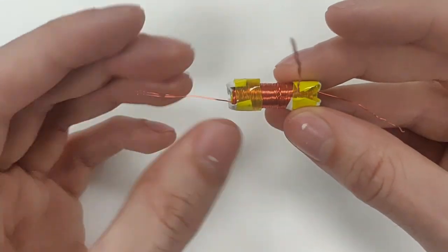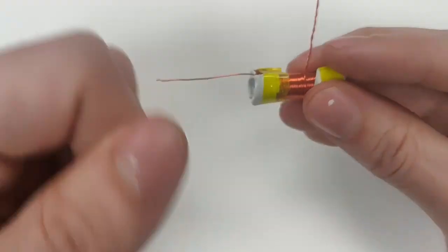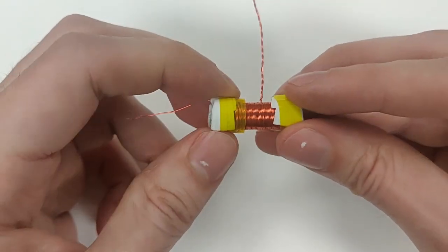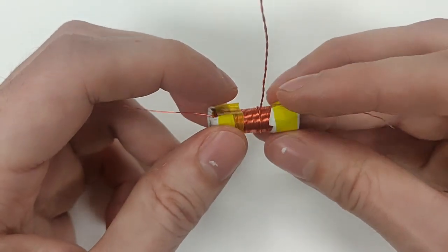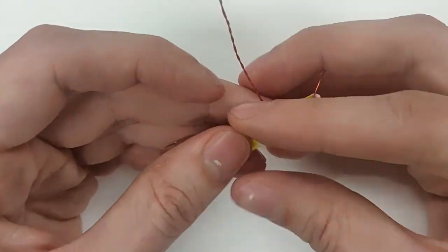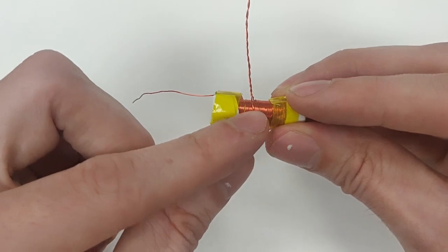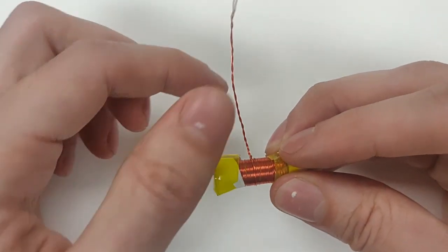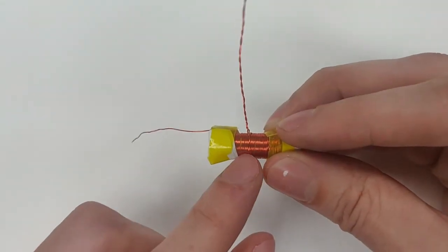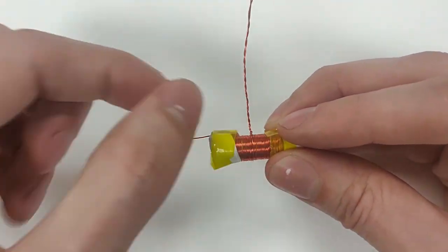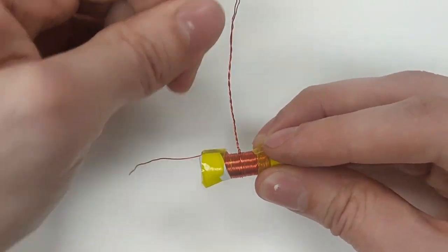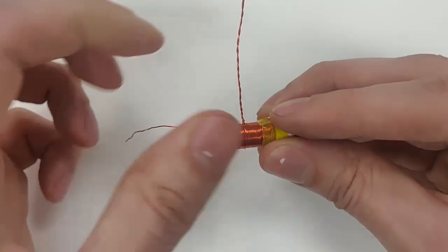Once it was wrapped in the paper, we wrapped the copper coil around our ferrite, starting from this end right here, and going about 30 turns until we reach this point, and we create this center tap, which is just an extended piece of wire. So if we were wrapping it, we'd make a longer piece and then keep wrapping it again.